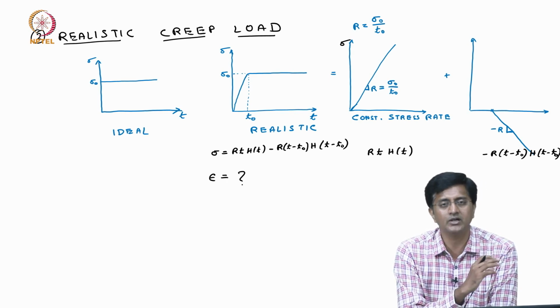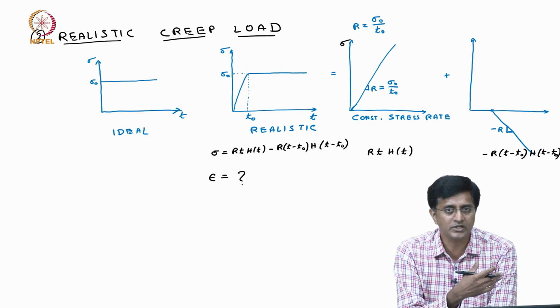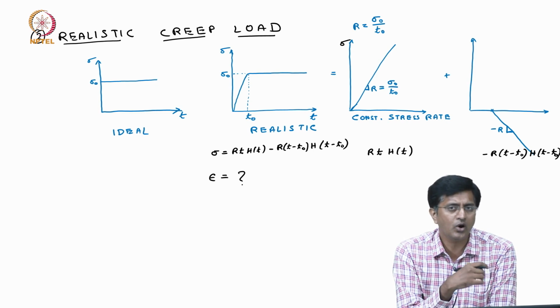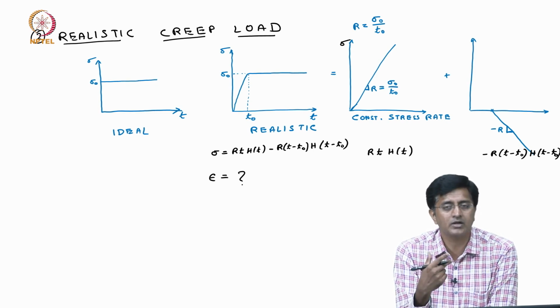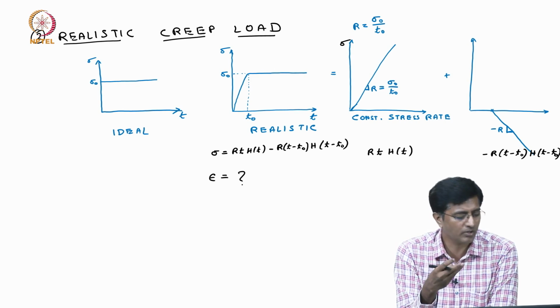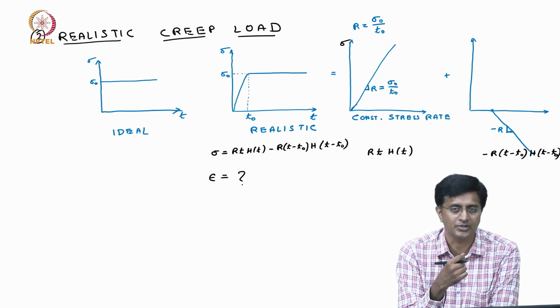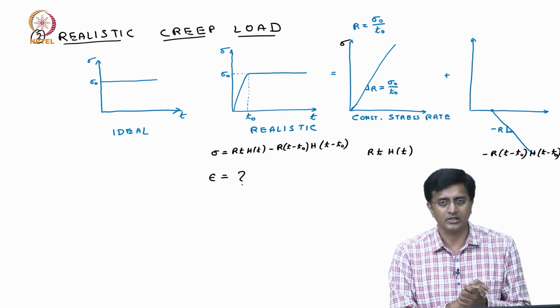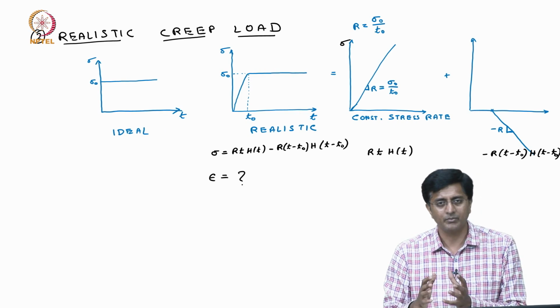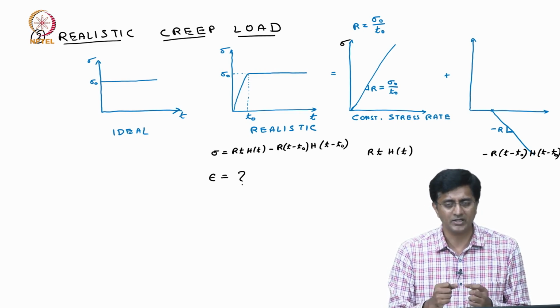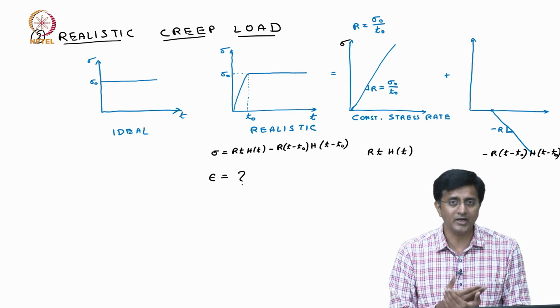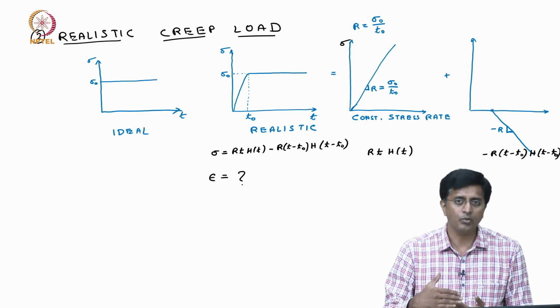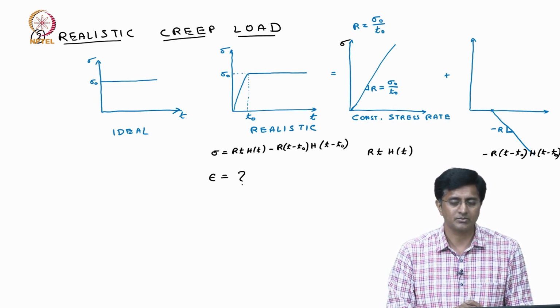But once we have the stress strain relation and we have also shown you the response under creep load, we showed you how we can invoke the superposition to solve some other loads such as the creep recovery and the realistic creep load shown here. So, until now we have only shown you the Kelvin and the Maxwell models, which are considered to be basic, but in order to model the real polymers we have to go beyond the Kelvin and the Maxwell models.